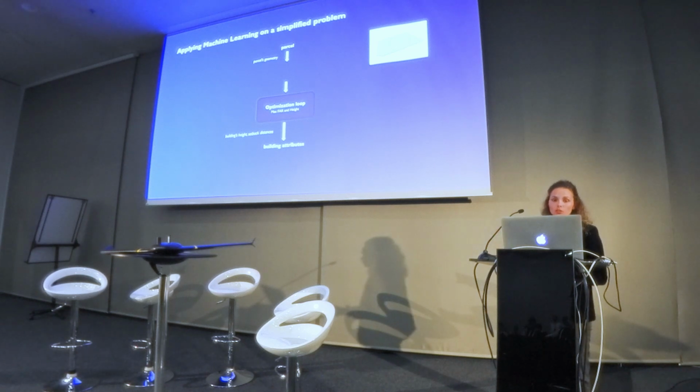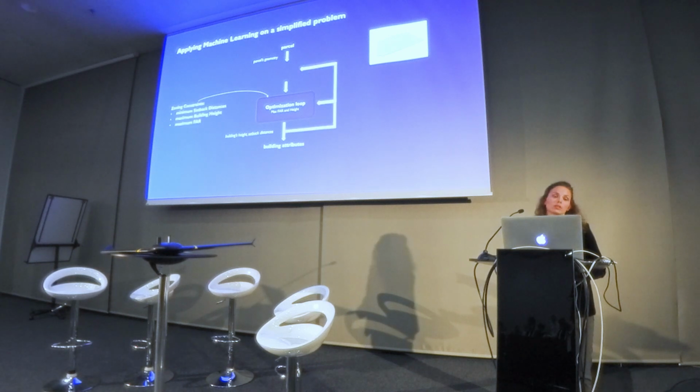What you can notice here is that we have a multi-objective optimization. That gives us a more realistic building at the end. So in addition to specifying the optimization goal, we're going to consider some zoning constraints, which are the minimum setback distances, maximum building height, and maximum FAR.